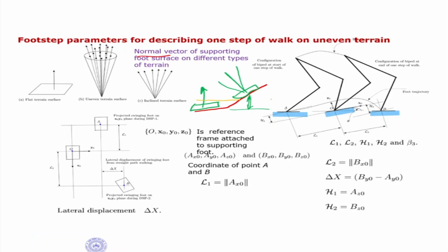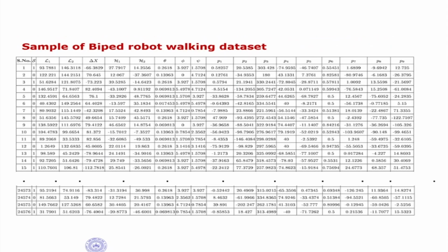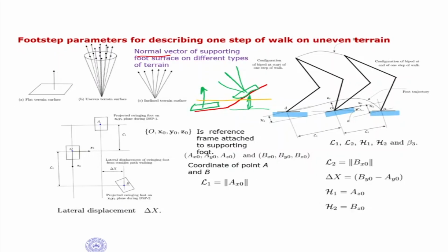I can take an average plane somewhere in between and then see if the 0 1 point is being satisfied. Okay, so that needs to be done for the case of 3-dimensional terrain. Now the problem here is that there are too many variables. In the previous case, you were just playing with the ankle trajectory or the hip trajectory. Now the ankle trajectory also depends on the terrain you're walking on. In the previous case, it was flat, so that problem was not there.